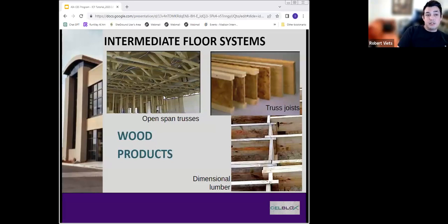So you can still pour your exterior envelope all at once, like 2 stories high, and then have your implanted truss cradles, and then just drop your trusses right into the interior, and speed your project up, just be rocking and rolling as you're moving forward.